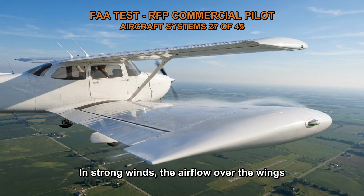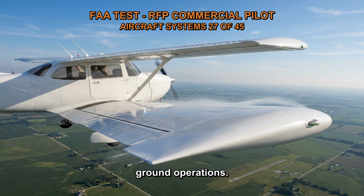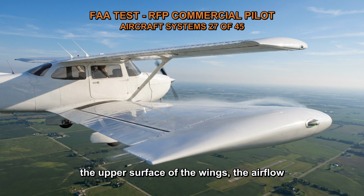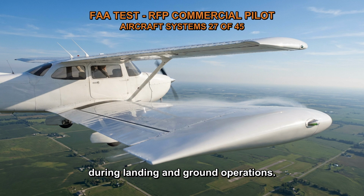In strong winds, the airflow over the wings of an aircraft can become turbulent, creating a challenge in maintaining adequate control during landing and ground operations. By extending the spoilers, which are located on the upper surface of the wings, the airflow over the wings can be disrupted and the lift reduced. This helps to increase the aircraft's weight on the wheels and improve traction, providing better control during landing and ground operations.